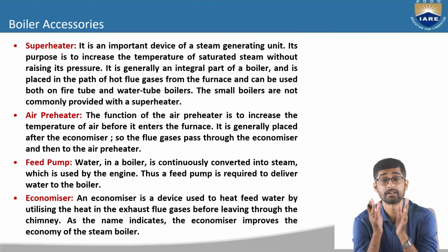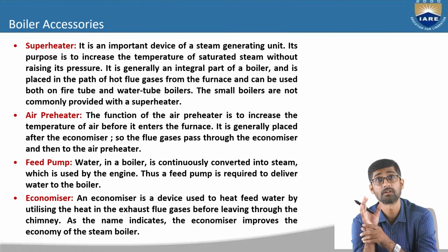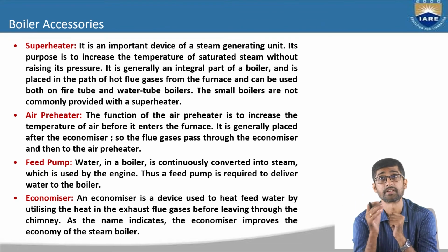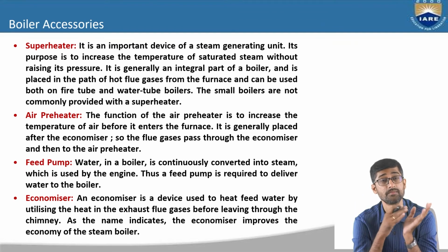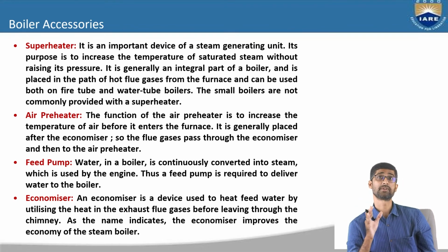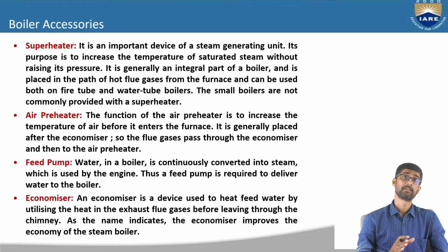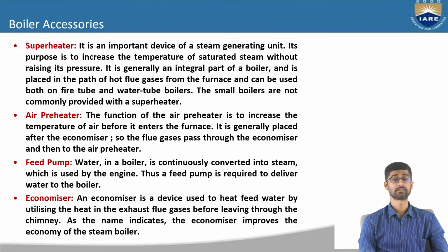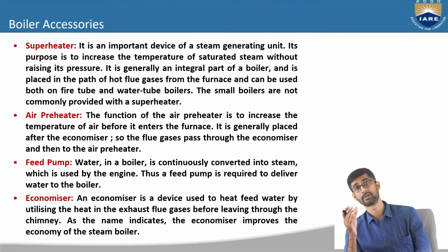It is the most important device of a steam generating unit, right? It is generally an integral part of the boiler, as I have told, and is placed in the path of the hot flue gases from the furnace and can be used both in fire tube boilers and water tube boilers. Small boilers are not commonly provided with superheaters. It requires large boilers. You have to use a superheater in a boiler if the boiler is large, not for small boilers.